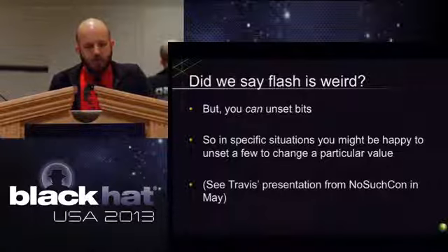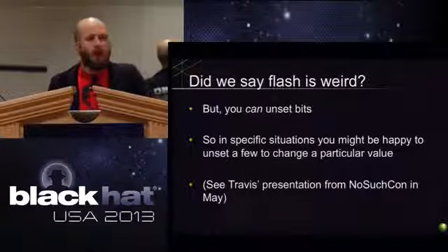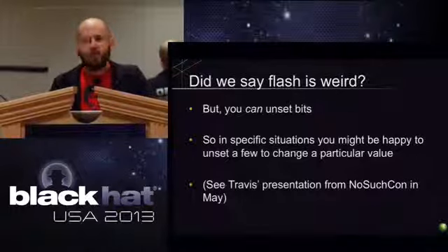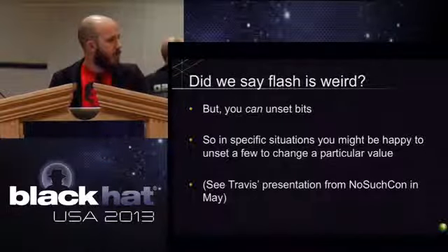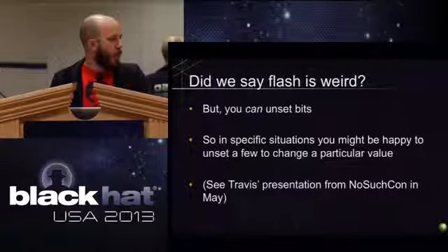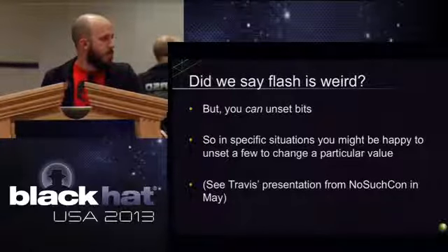Right, so we can unset bits. In certain specific situations, you can be happy with not having to do that mass erase trick. You can craft that in a binary 1 and 0 format, you can still flip from a 1 to a 0 and then recraft your data. But that is a huge headache.